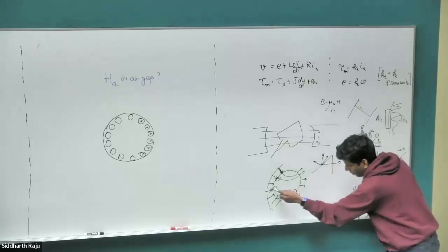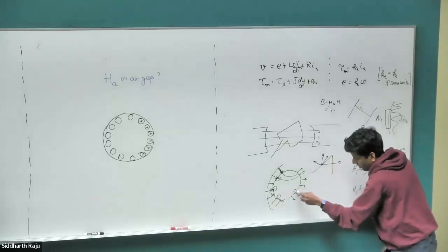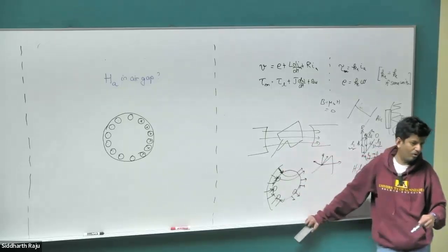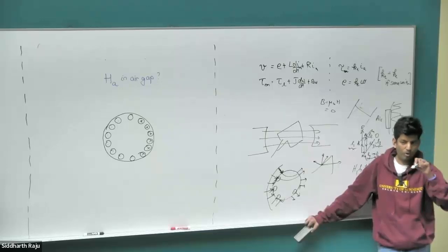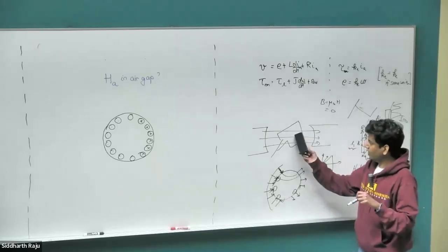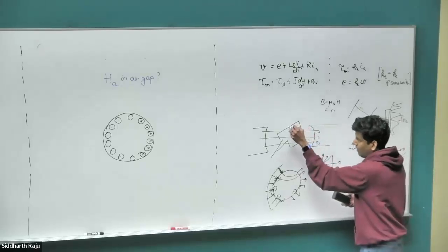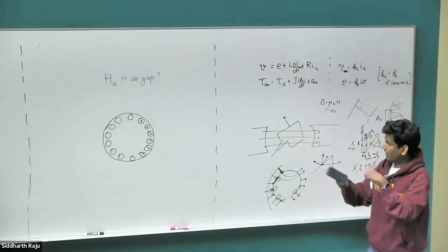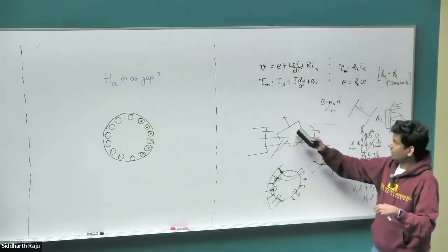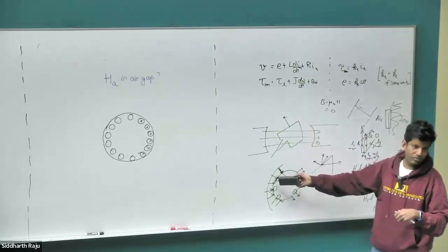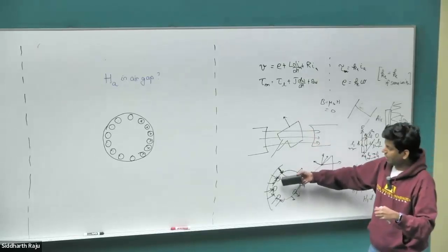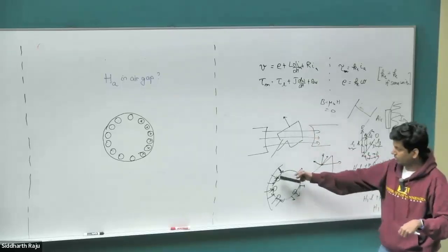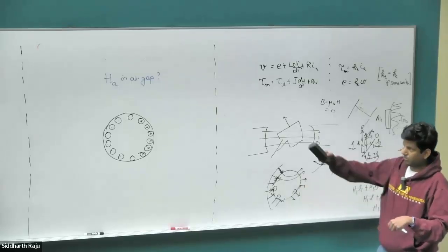So the torque or the force on the conductor at every single point is going to be in such a way that it's purely tangential. All the component of force is only tangential. There's going to be no normal component. And this is what I mentioned in the diagram that we drew. I said that there is going to be an enormous amount of force created on the winding. But in a practical motor, you do not even have to have too much of a retention sleeve to counteract this force, because that force would not exist at all in the first place in an actual motor. We still do put the retaining sleeve because of the centrifugal forces, but not for the normal force, because the normal force dissipates away completely since it's always perpendicular. Right? So the cos alpha term, that's the reason it disappeared.